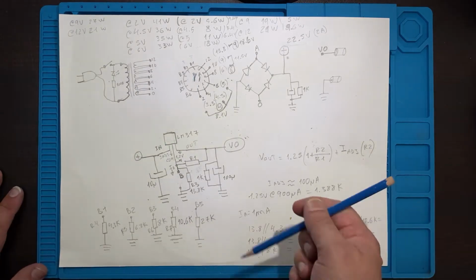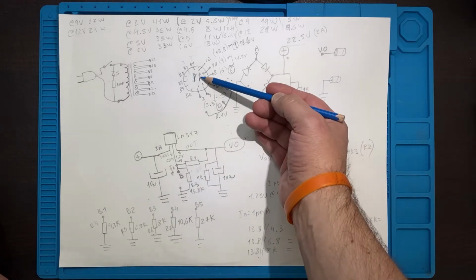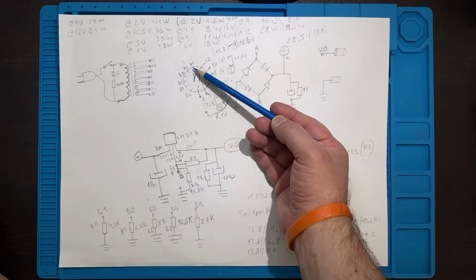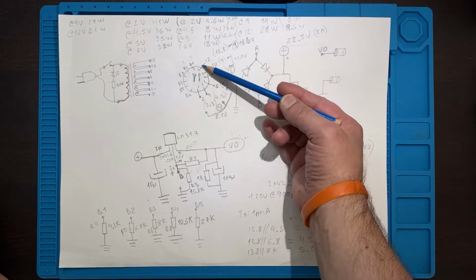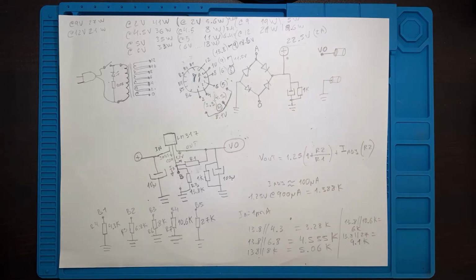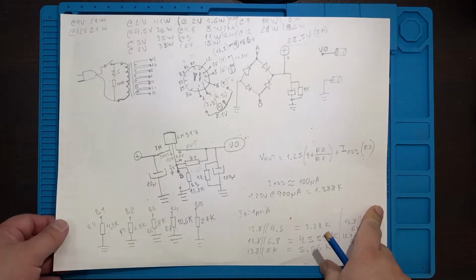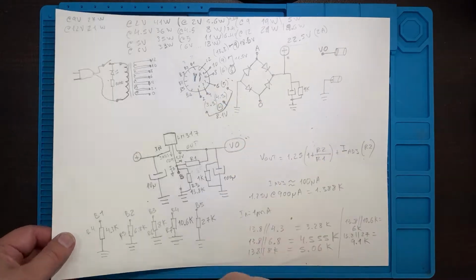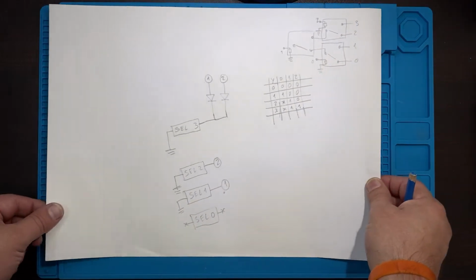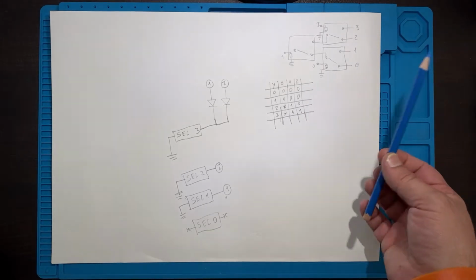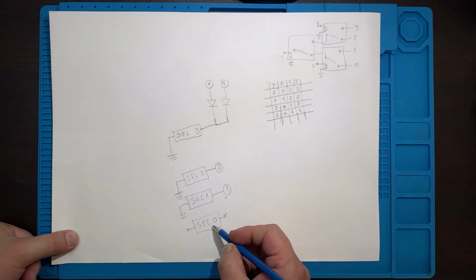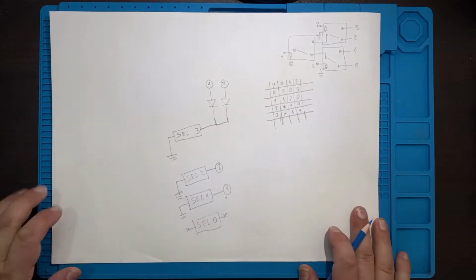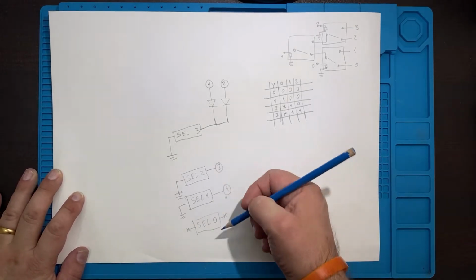So I had to use A to ground for this resistor, and what I get on the other side is actually 1, 2, 3, 4, 5, 6 connected to ground as well. So I had to use a way to select the secondary on the transformer with a ground connection. So I had to use 3 relays to do that. And it's basically a logic circuit. So I have 3 relays. Select 0, 1, and 2 are the relay coils.